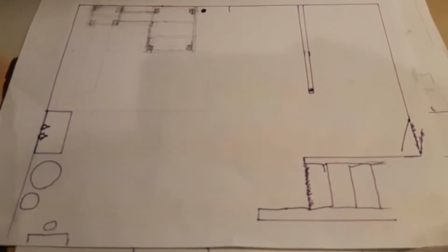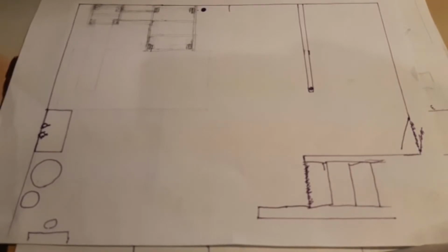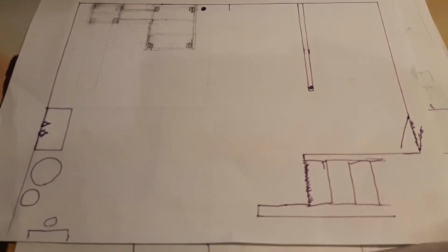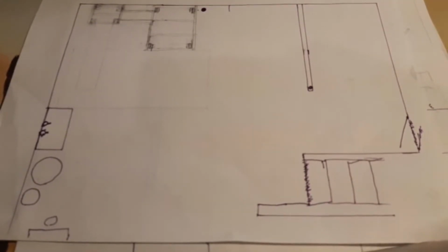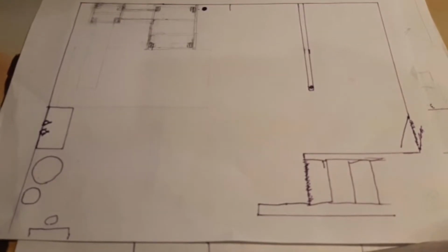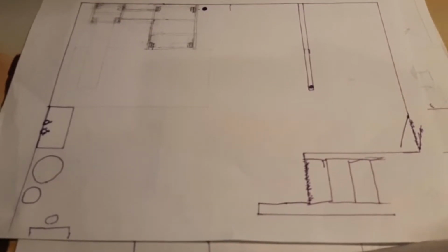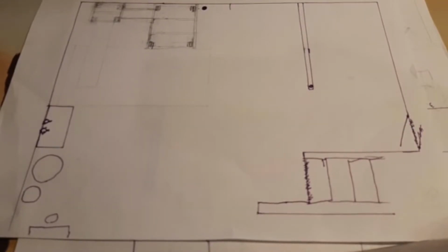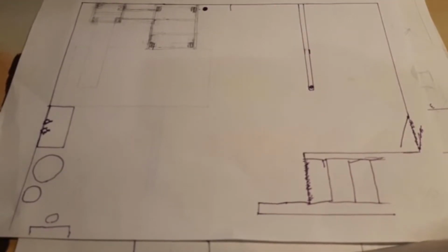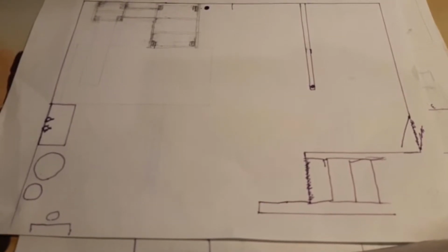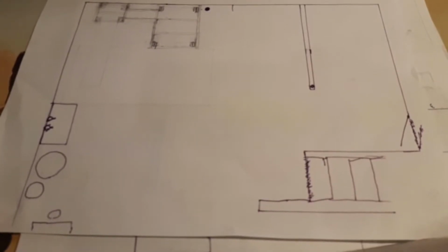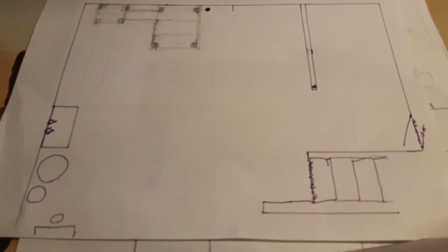So the very first thing that I did with this project is really understand the space and the problem. So we have this big empty space in our basement that we would love to put some kind of a play structure in. But first I really needed to understand the space. So what you're seeing here is a scale diagram of the basement space. And what I did is I went through with a tape measure and measured everything out to very quickly scale it down. A very easy way to do this with a large space like this is I just took my ruler and every foot that I measured, I just marked out with a centimeter on here. So every centimeter in this diagram represents 1 foot in real life.